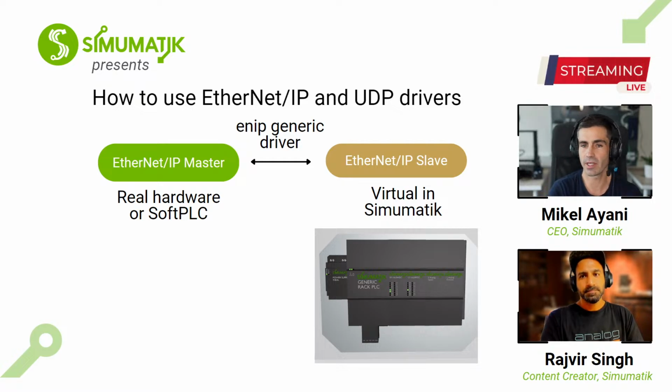So the thing is that all these native protocols, the way we use them in the gateway when we develop drivers, is that when you start the emulation in Simumatik, these drivers will connect to the PLC. It could be a physical PLC or just a soft PLC, and they will read and write memory addresses. Okay, that's how it works.